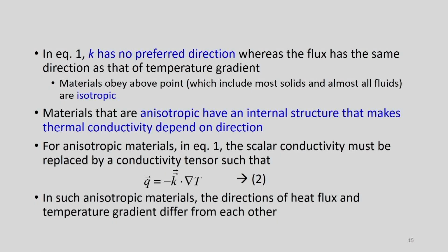For these anisotropic materials, the flux is related to the thermal conductivity tensor. Now, this has an orientation, and depending on the internal structure, it can have different directions also. So, now k, thermal conductivity, is a tensor. So, q is nothing but the dot product of this tensor and the vector del T, right.